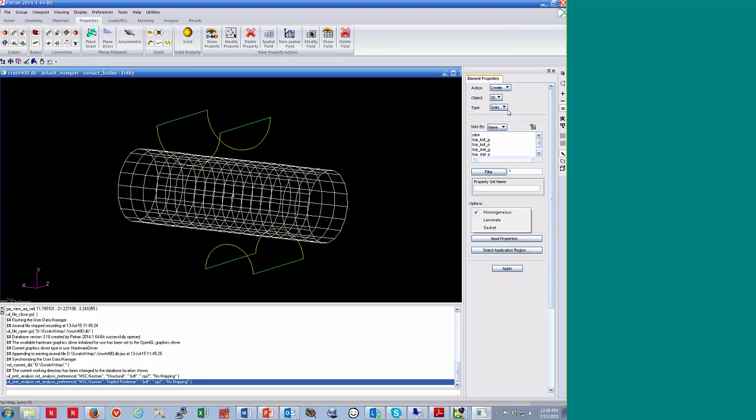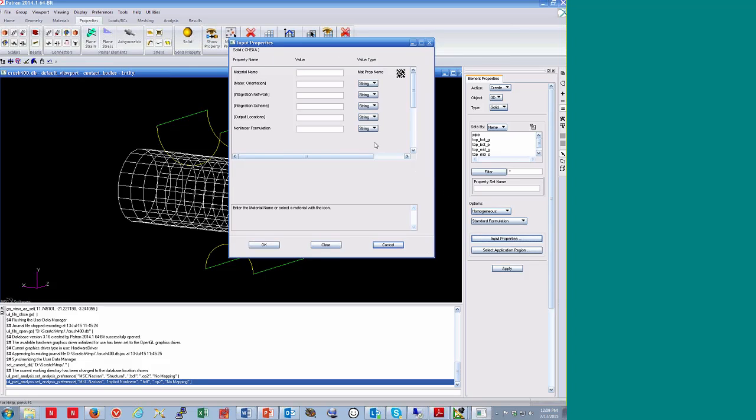One thing I would like to point out when you're setting up element properties is that when you go to the properties form, you'll likely see a nonlinear formulation option alongside the standard formulation. If it's not a standard formulation, it's going to set up your properties so that it will write out the property extensions. If you're familiar with Sol 400, you know that you write out something like a PSOLID, but if you want it to be nonlinear, you also have to write out an extension card, say a PSOLIDN1 card in this case for 3D.